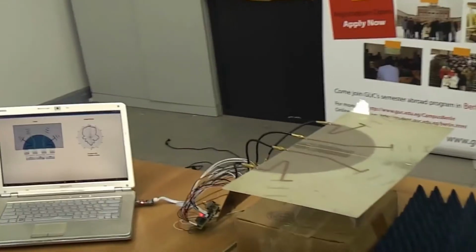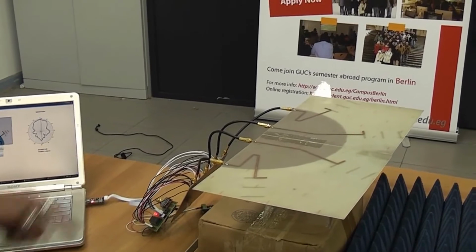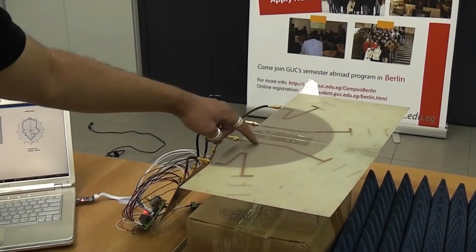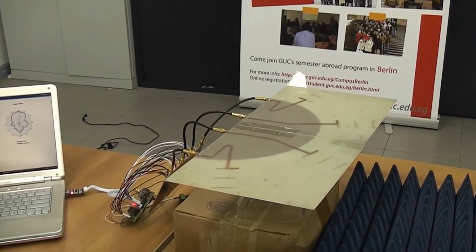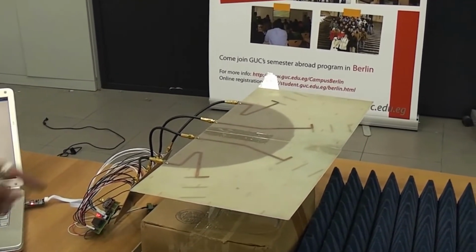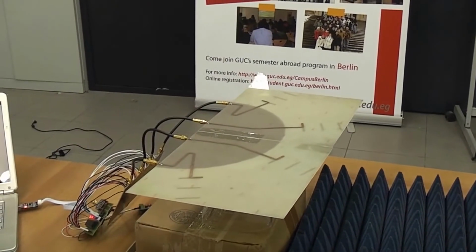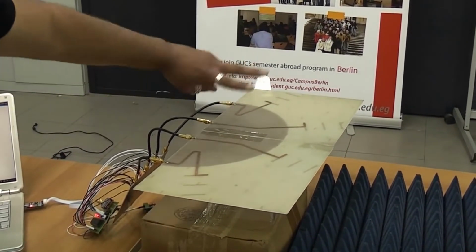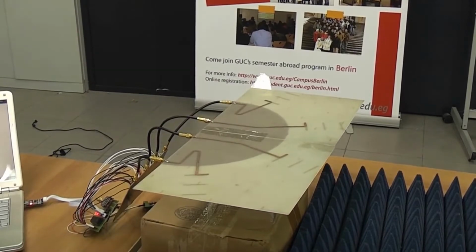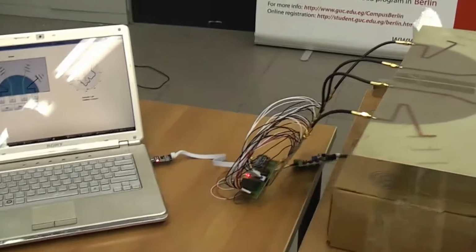As we can see here, our transmitter is composed of a printed Yagi antenna array. The array is composed of 4 elements, 1, 2, 3, and 4. This array is able to produce up to 7 different patterns, starting from radiating from every single element and going through radiating through 2 consecutive elements. Actually, we can acquire this through our feeding network.